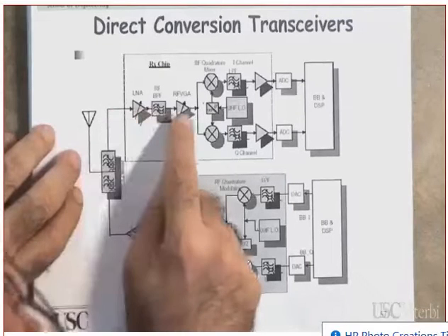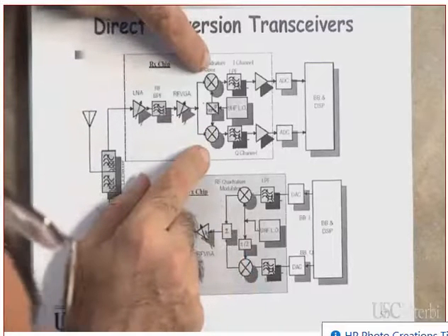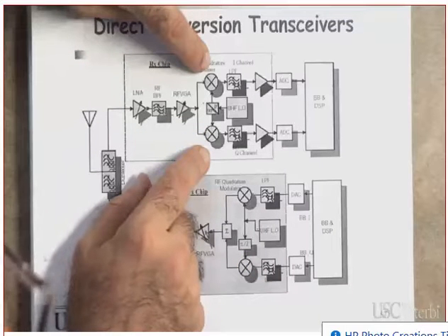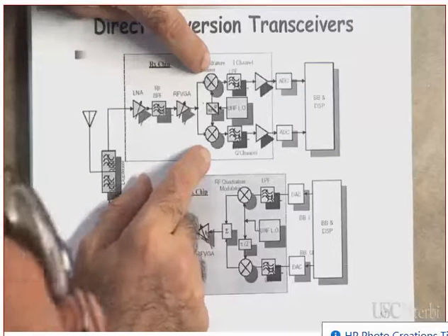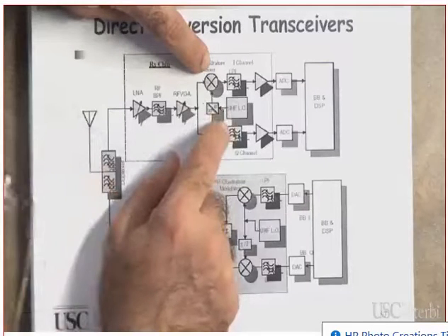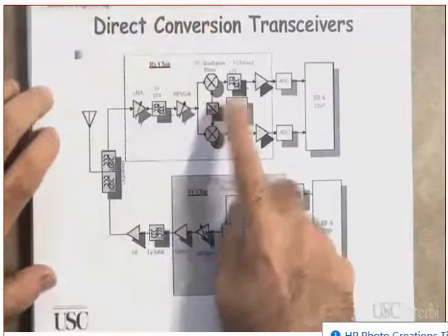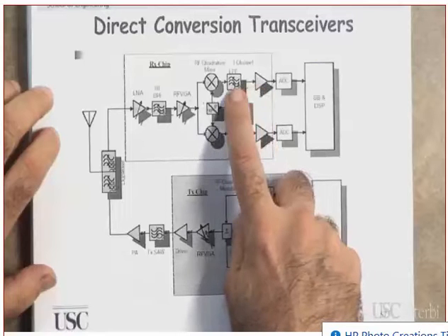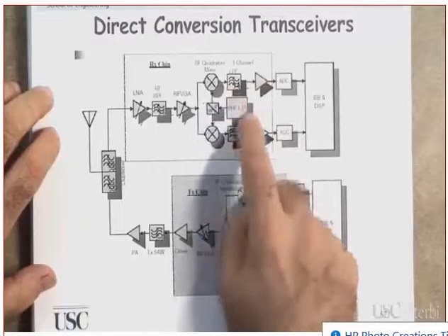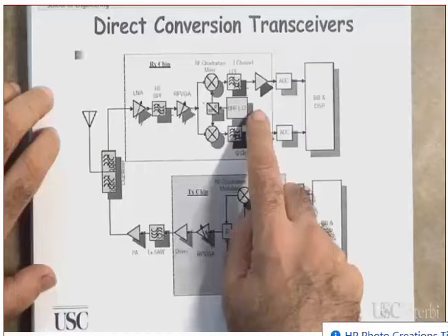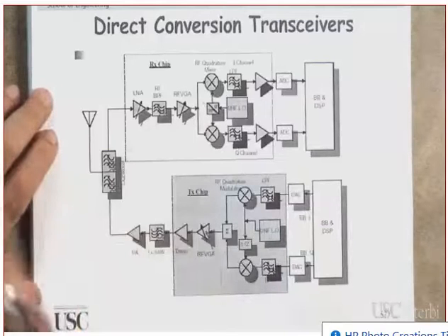Okay, so the LNA, the filter, and again, a variable gain amplifier. What am I doing here? I am mixing I and Q. In which range, in RF or in baseband? RF, which means the design of this one is going to be critical. Clear? And then, I use the low pass filter to get rid of the sum, and then amplify it with the audio amplifier along with the ADC and stuff like that. Clear?